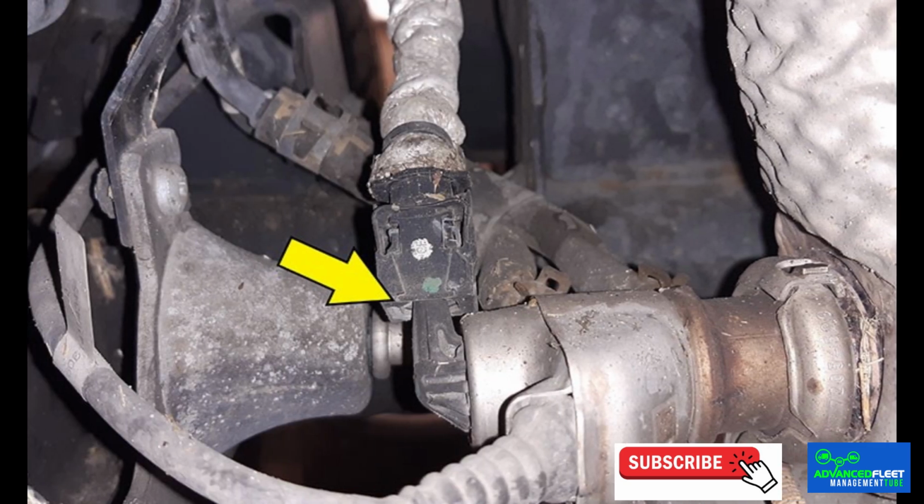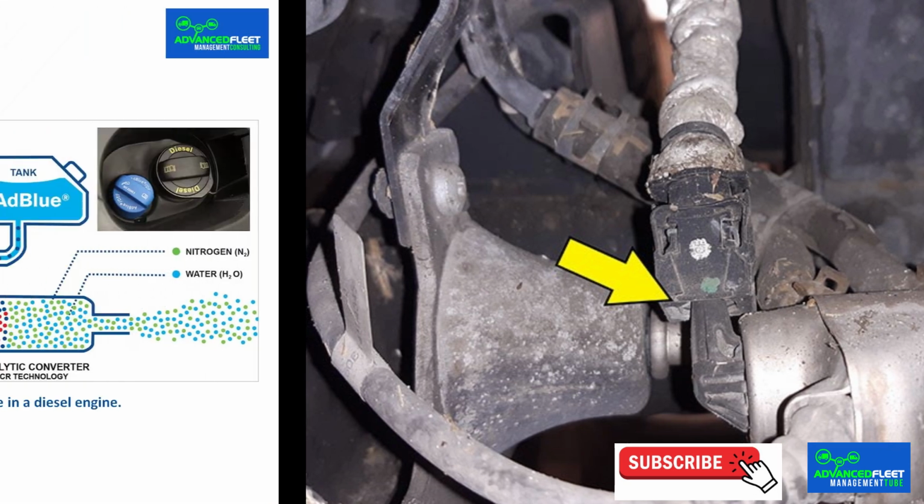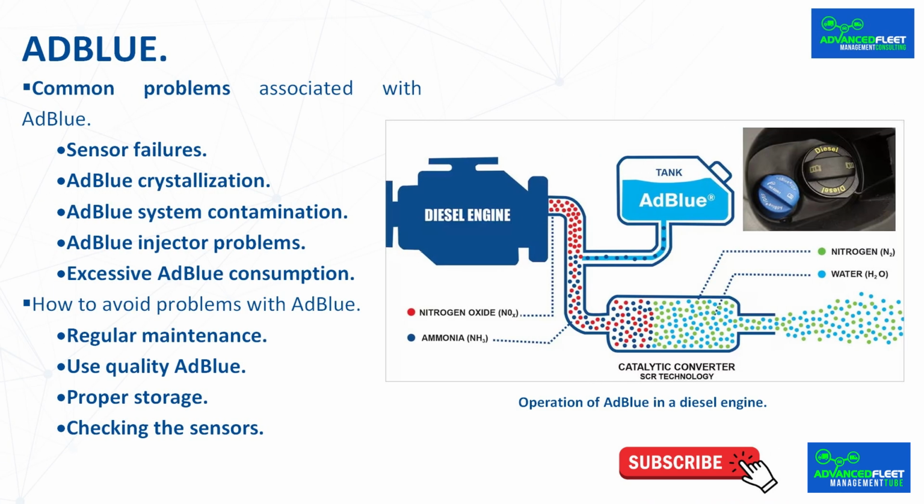Excessive Adblue consumption. Excessive Adblue consumption may indicate the presence of leaks in the system. Any leaks should be identified and repaired to avoid unnecessary costs and ensure the correct functioning of the system. How to avoid problems with Adblue. To avoid these problems, you should follow these tips.